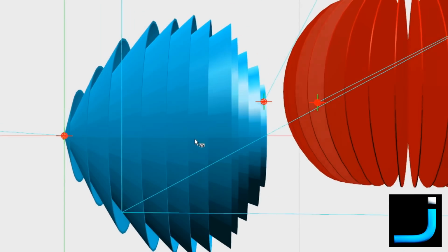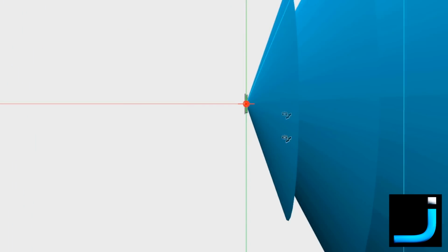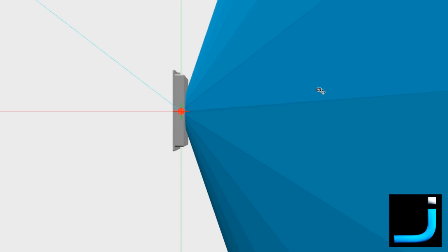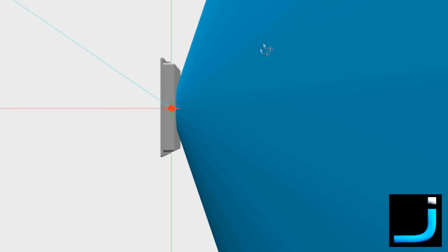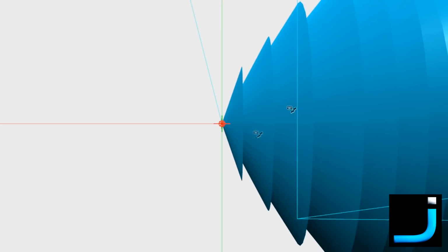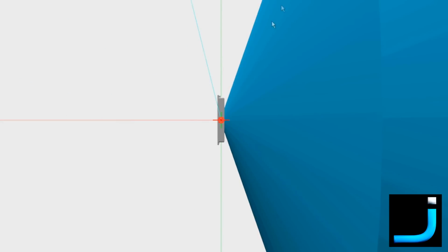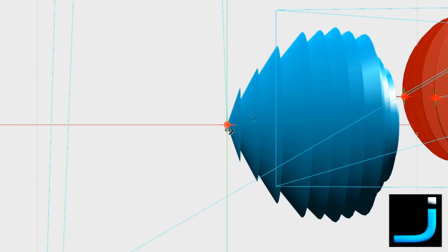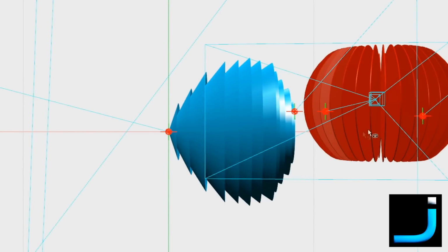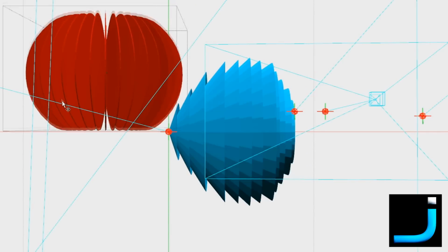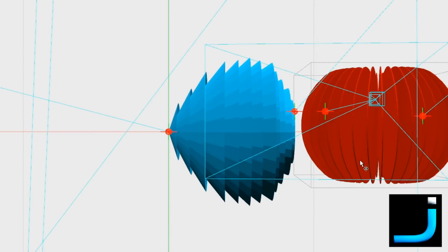And again, remember we're on a patch antenna here. Because it's 8 decibel, it's not omni. So we have to make sure that we're pointing the 8 decibel circular antenna at the aircraft. It emanates from the face of it. So there's no good flying behind us or anything. It won't pick you up.